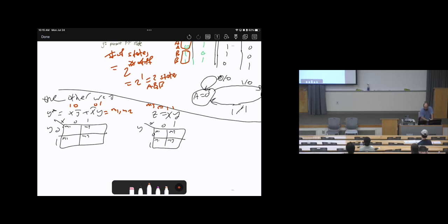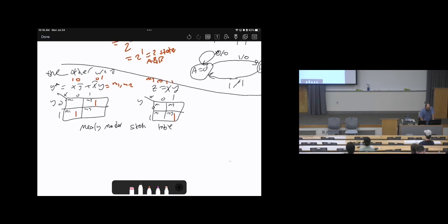We know how to deal with K-maps. So with y star, it will be ones at M1 and M2. Then here, the 1 will be at M3. So how can we write this into merely, not the generalized model, merely the Mealy model state table, which includes the present state y, and the input x, which can be 0 or 1.